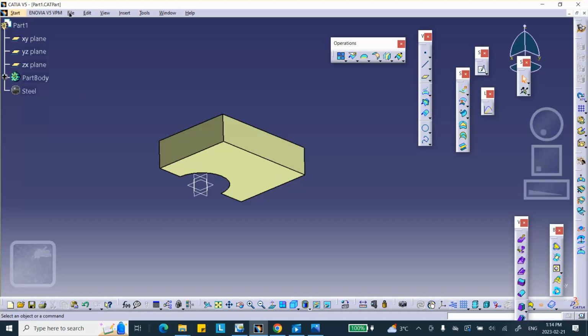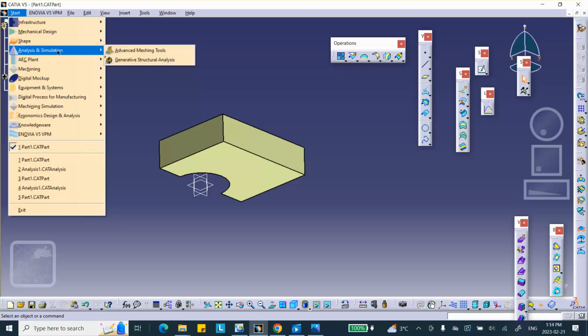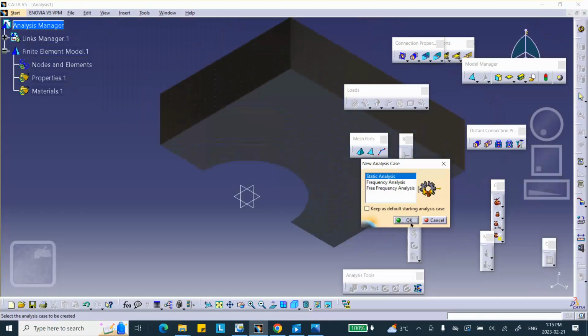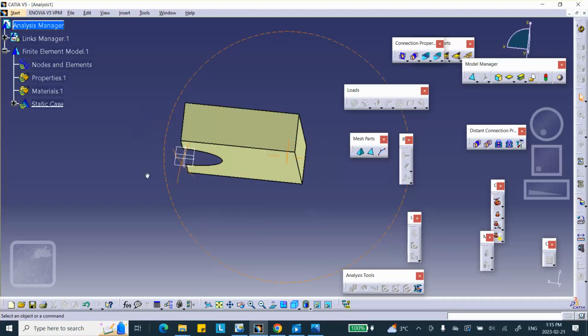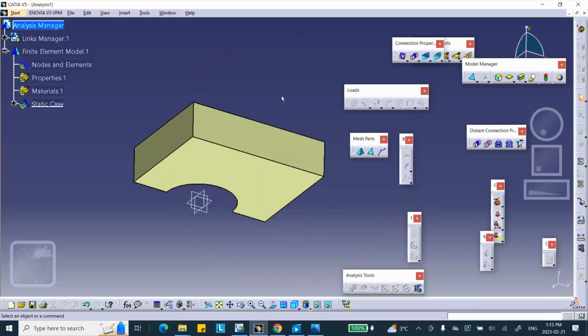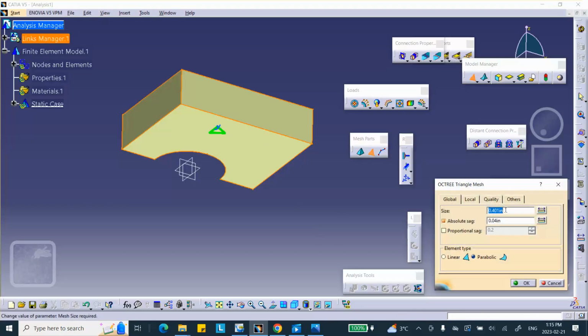So we're going to go to generative structure analysis. I'll do not a fancy mesh, but just a regular 3-noded triangular element, or parabolic one, 6-noded, whichever you feel like. Right there, you can see this. Okay, let me do this and that, and parabolic. Why don't I select the find a mesh around this hole? How about that? I like to do that.